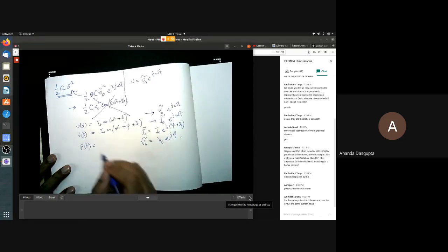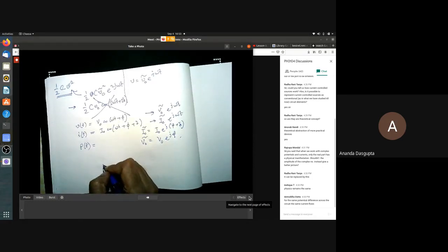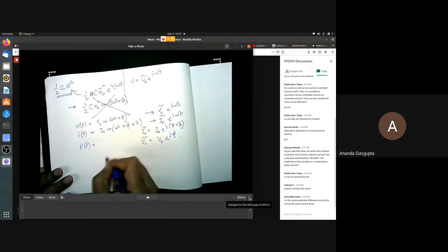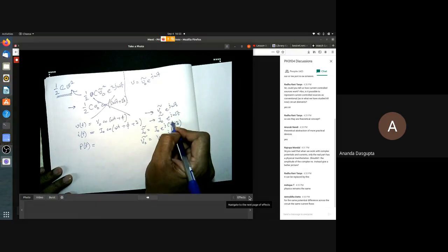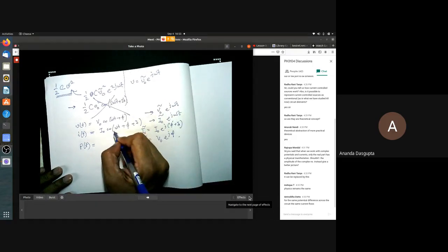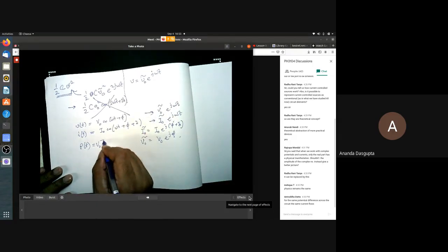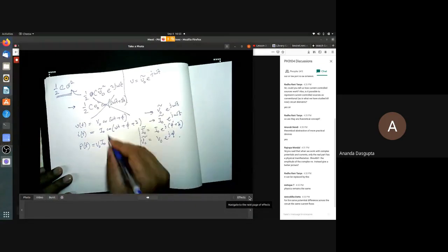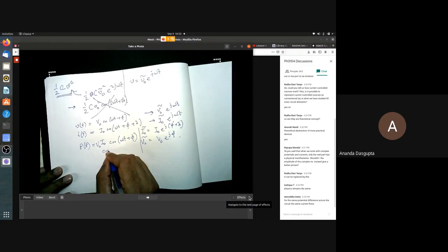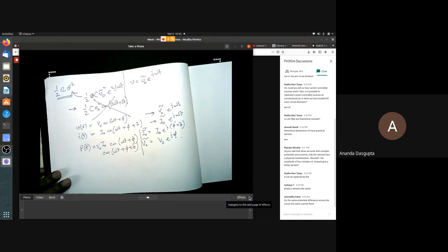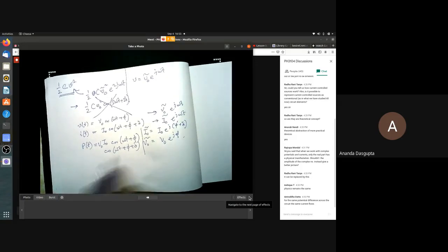Now, what is the power? You can think of the power as, of course, voltage times current. But which one do you multiply? Do you multiply these two? Of course, you don't. You multiply these two. So the actual instantaneous power is, of course, V0 I0 into cosine(omega t plus phi) into cosine(omega t plus phi plus delta). Now, this is exactly correct.